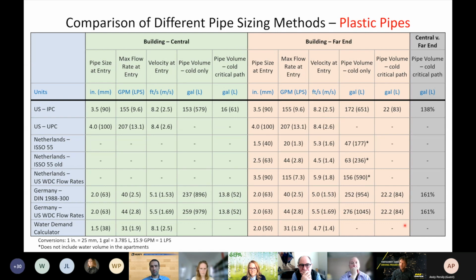And another thing is that by traveling through the building, due to all the good proper energy saving codes nowadays, we have in the meantime warmer and warmer shafts. And therefore we also recommend to separate hot and cold water pipes in two different shafts, so that the cold water temperature increase by picking up the environmental temperature is decreased. And this is also critical to the distance the water travels through the building.